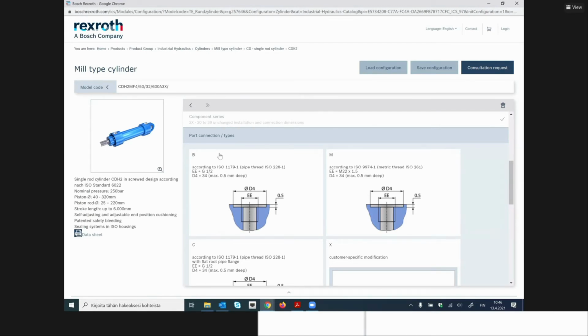But I would say that a good safety factor in this case is something between 2 and 3. Yes, but we have many kinds of safety factors, and in this case the first one is the most important. That is the buckling under the pressure that the load makes, the load that you specified, and what buckling safety factor comes in that situation.